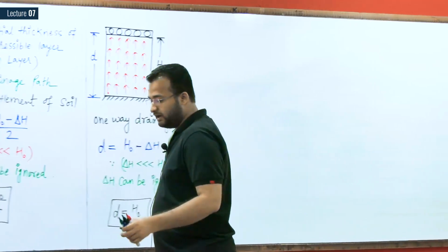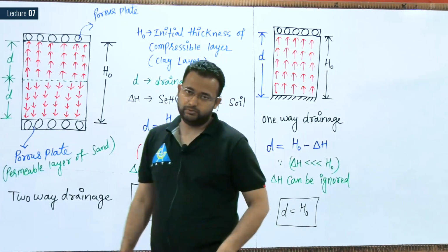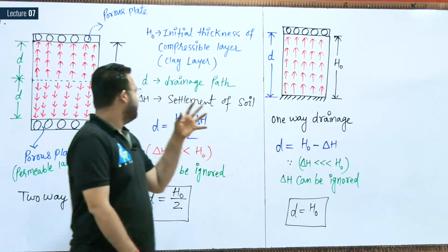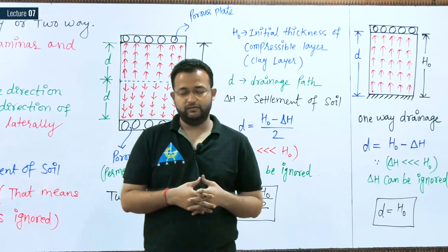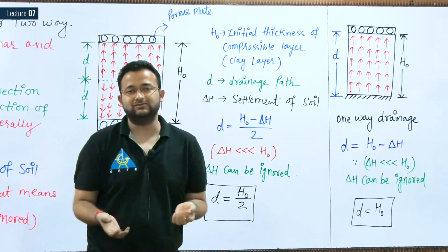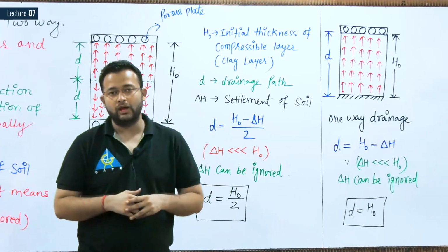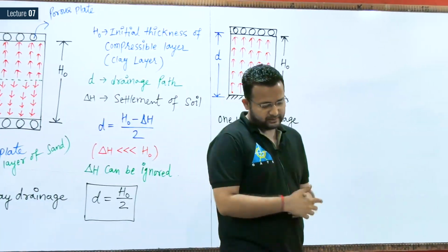So till now we have discussed the experimental setup. Suppose we are going to perform the consolidation test, we should have one hollow cylinder of this much height, which is not actually a cylinder but is called a ring, the consolidometer. Sometimes it is also called the fixed ring.